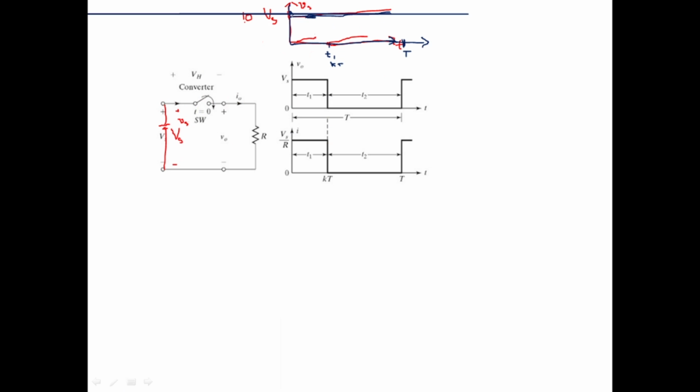Now this is V0, correct? If you call this as I0, it is correct. But one thing I will tell you, this V0 is Vs if you consider chopper loss is 0. If you consider there is a loss across chopper, and if you call that V chopper, means if it is a 2 volts drop, V chopper becomes 2 volts.